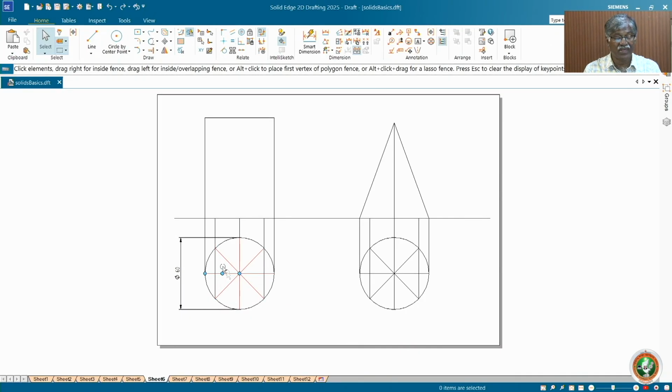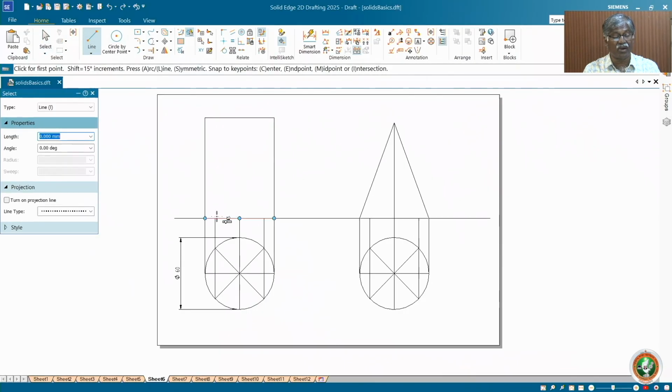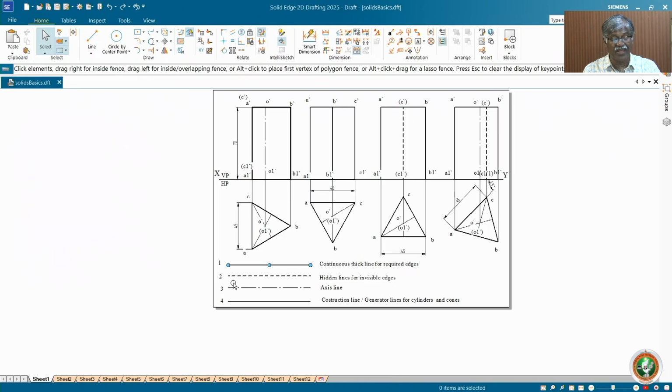You know how to create this. You take the circular pattern and array. You can do it and project it. Now, what lines should be drawn dark and light? There are imaginary lines. Imaginary, like construction lines only, you can use. Now, construction line, axis, construction line. Preference is axis, not the construction line, as per the 4 preferences I have given earlier. See, here I have given 4 preferences. Visible line, then invisible line, then axis, then construction line or thin line.